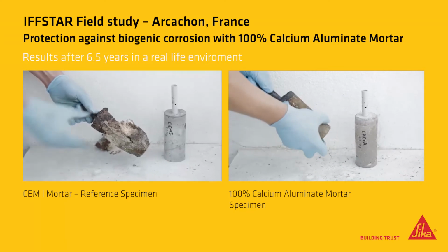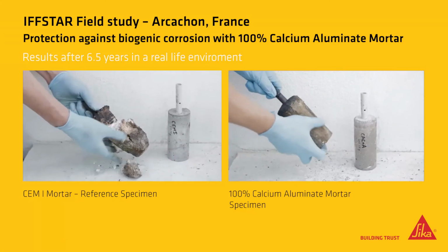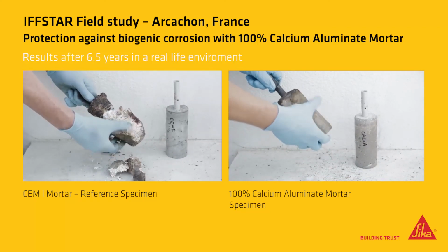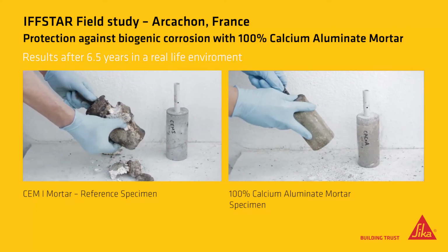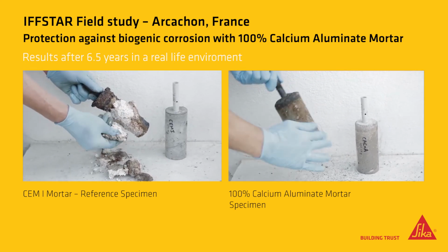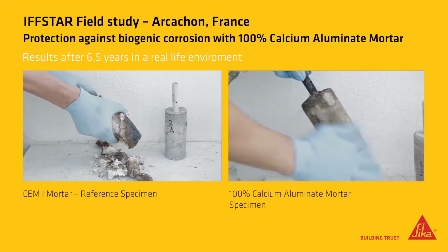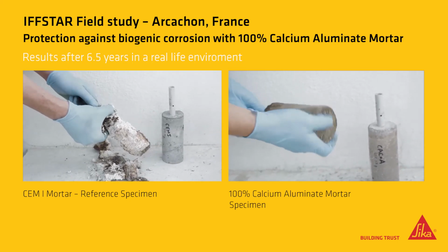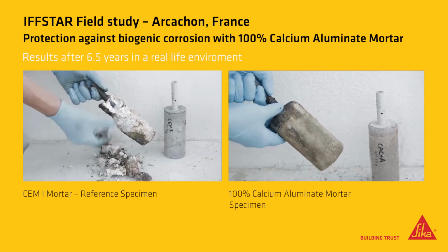Both videos show clearly the difference between the Portland cement specimens and the one made with 100% calcium aluminate. The soft material that is easily removed is gypsum. Remember the video taken in a large collector, presented earlier, regarding the inspection with the owner. The soft material which was removed was also gypsum.